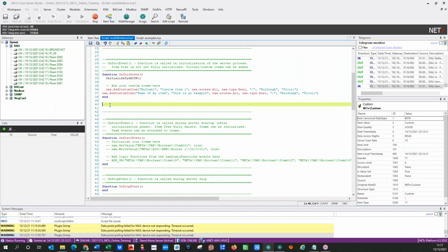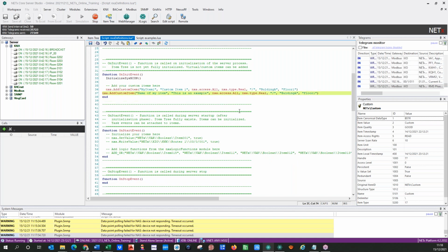And following this example, if you filter and you write, for example, NXA dot and you press Control and space, you will only filter all the specific functions related to NX Automation or created by NX Automation for the Lua engine. So knowing that, if I delete this and I write now NXA.access dot whatever, I press Control and space and I filter the options I have to choose. That's the trick. So you can also copy paste and investigate what is possible for you.